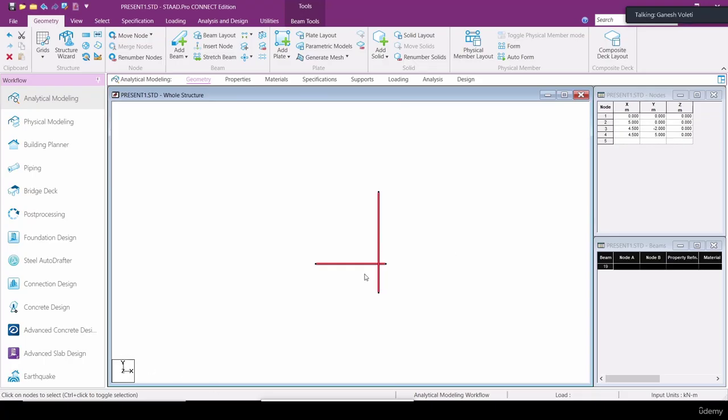If there is some z distance, you cannot observe it in this view, right? That limit is called the tolerance limit. In intersect selected beams, if these two are separated by a z directional distance of 1 mm, they can be connected.